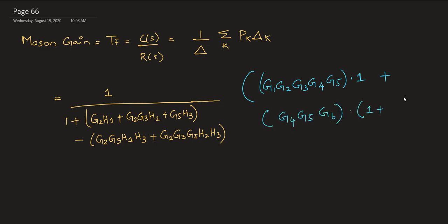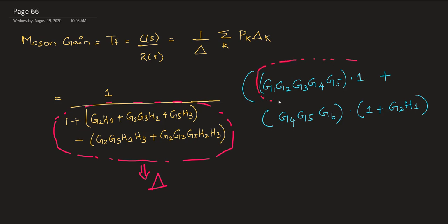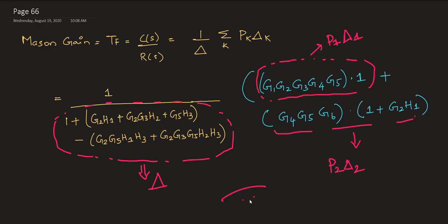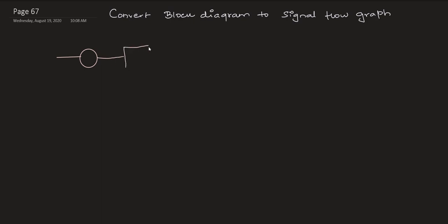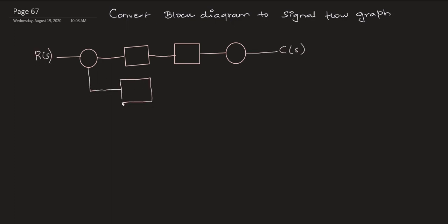Good. So that is how you solve a problem on signal flow graph and the reduction of signal flow graph using certain rule sets. Here we are following the Mason gain simplification, right? When you apply the Mason gain formula to the signal flow graph, you are simplifying it. This simplification is considered much better than block diagram simplification, because it is less error prone, and everything is predefined and very systematic, right?